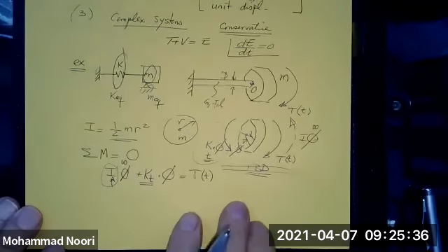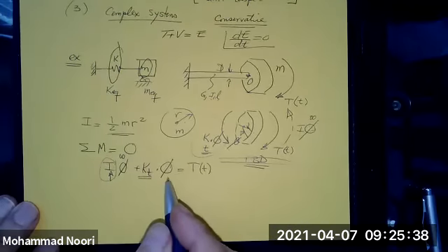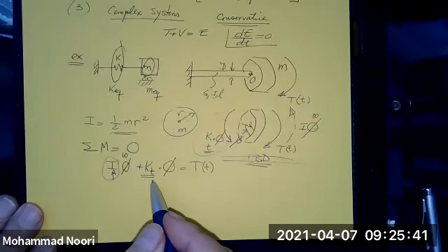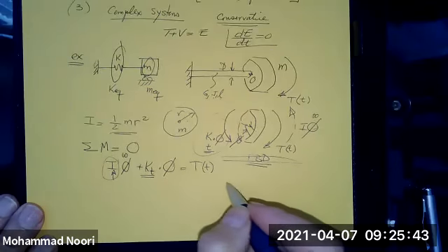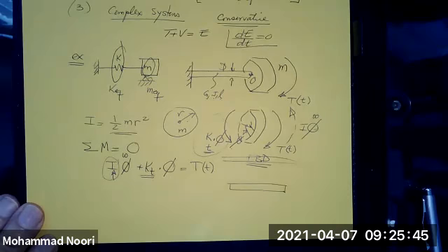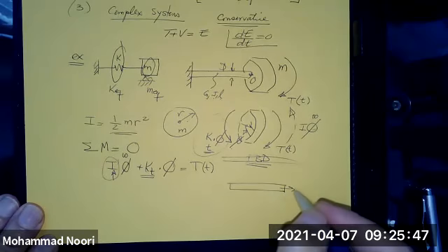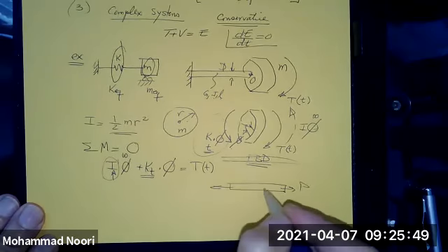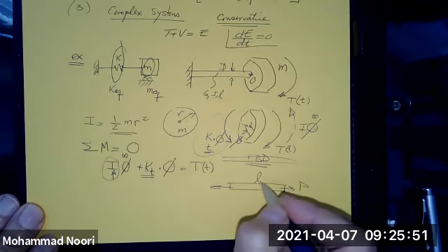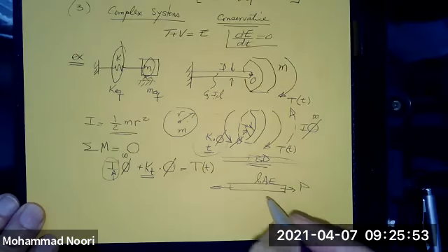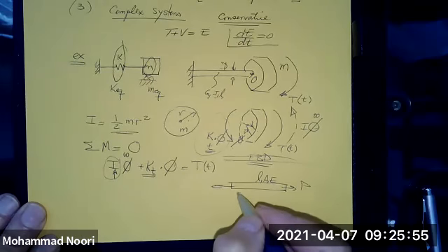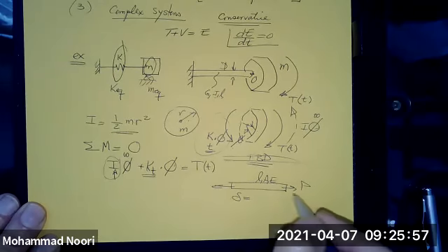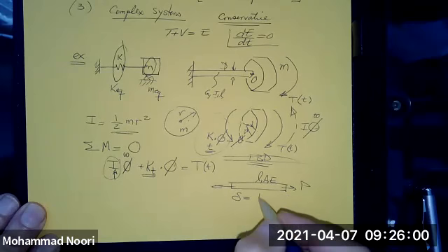Remember, we can use the concept of the definition of the stiffness. From strength of materials, you remember, if you have a load P acting on a bar of length L, area A, modulus of elasticity E, the deformation delta that this bar experiences was what?